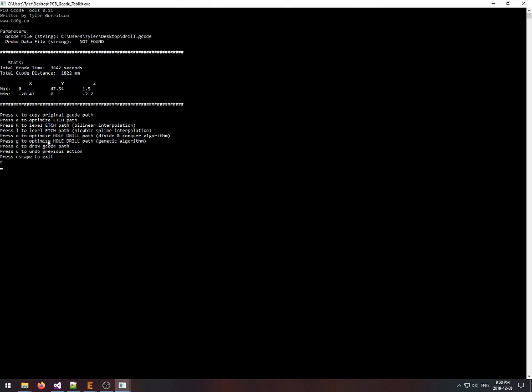There's two hole drill optimize tools. There's the divide and conquer algorithm and the genetic algorithm. The divide and conquer algorithm basically divides the board into different sectors and then uses either the genetic algorithm or a brute force algorithm, depending on how many holes, to create the most efficient path through all the holes. Basically, those are the two traveling salesman algorithms. The genetic algorithm tool just leaves the board whole and applies the algorithm to the whole board. So it can take more time to process the whole board. For time's sake, I'm just going to show you the divide and conquer algorithm.